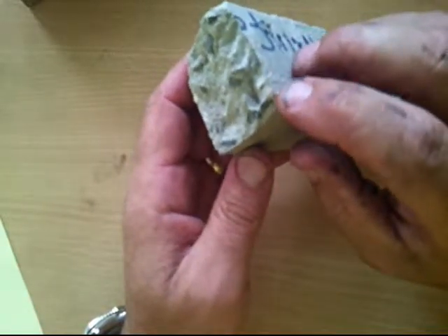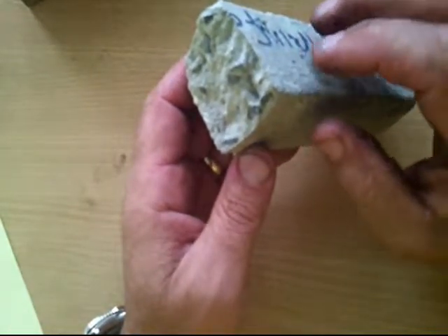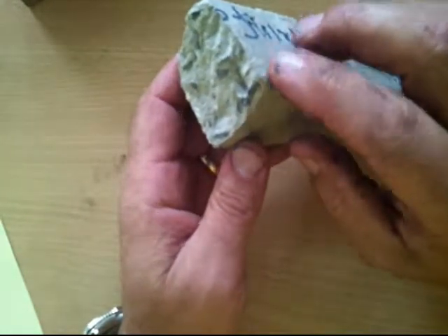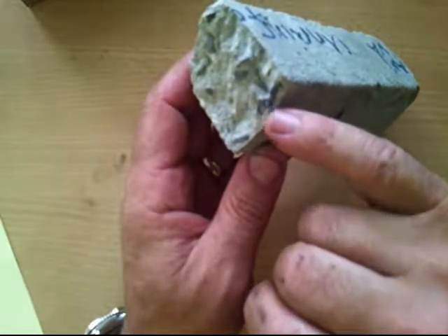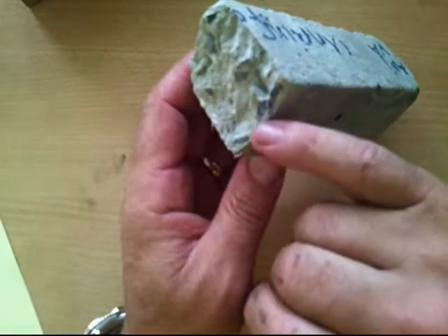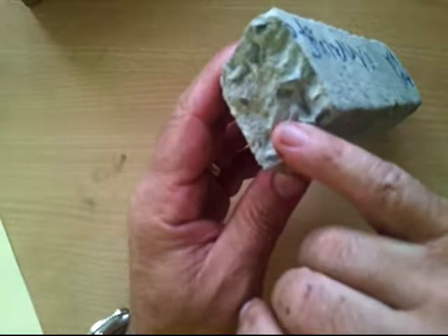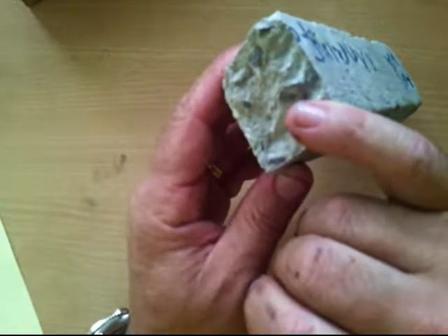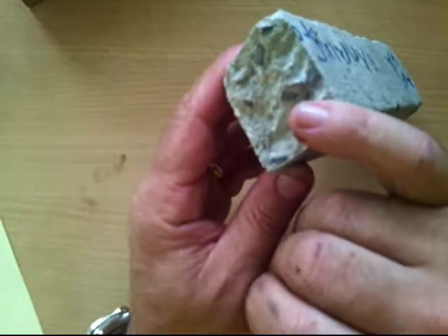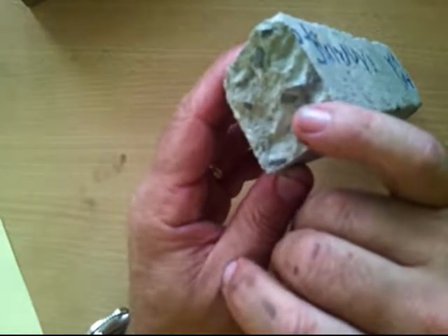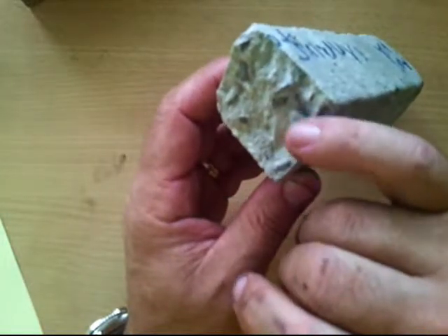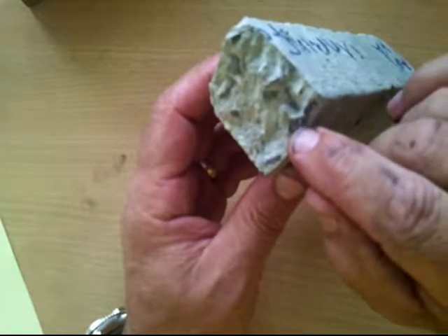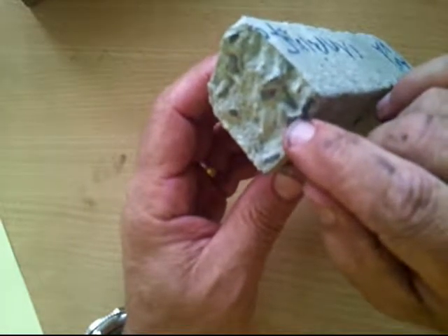The pozzolana relied on some crushed up volcanic rock, and it had a similar kind of process as using lime and other materials to be able to create a concrete. Now, Portland cement, the same sort of process. We have a cement, which is the matrix, and binding together particles of sand and of volcanic rock, igneous rock, like basalt, or I guess the common name is blue metal that's used, but it's really just a stone, not a metal. Very tough, hard-wearing stone. So the properties of the stone are desired.